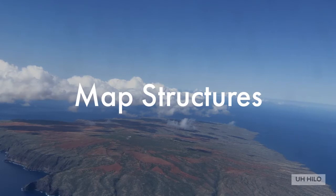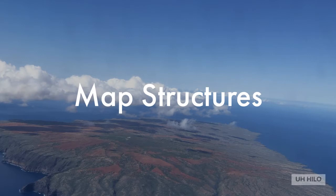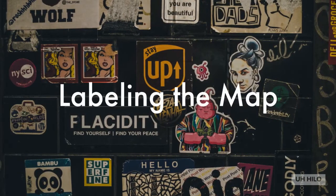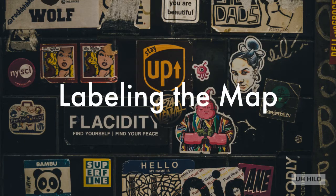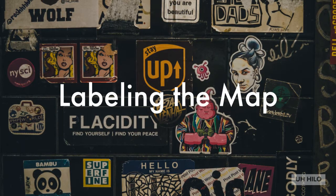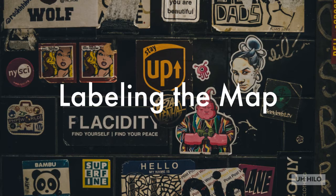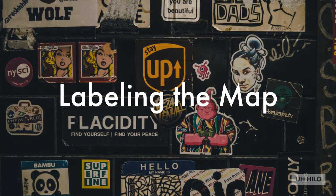In making the tables for these maps, we define a min term mi to go with the row i of the truth table, with i in binary as the variable values, so each cell of the map corresponds to a min term. For n variables, we're going to need 2 raised to the n squares. Each map is labeled in 2 ways. 1, with the variables at the upper left of the columns and rows, with a binary combination of these variables for each column and row, and 2, with single variable labels at the edges of the map, applied by a bracket to single or double rows and columns.